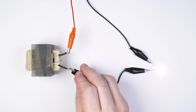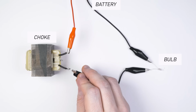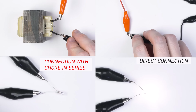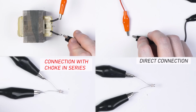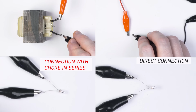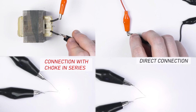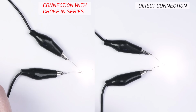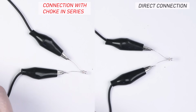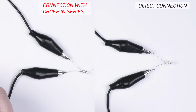Here you can see a light bulb, a choke, and a battery. Let us connect all these elements in series. As we can see, when the bulb is wired through a choke, it does not light up instantly, but with some delay. This is because the moment the circuit is closed, part of the energy is stored in the magnetic circuit of the choke, that is, it's being charged. When the core of the choke is saturated, energy begins to flow into the load.